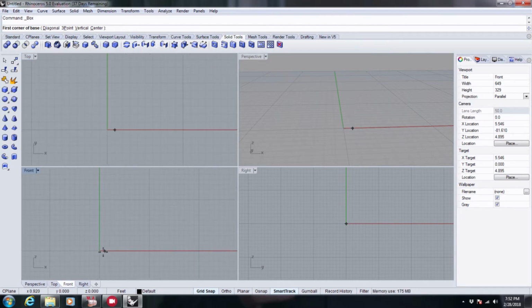Basically, you line all of your tiles up in a flat surface, then texture map them flat, and after they're texture mapped, you arrange all of your panels into their final position of the curve where they're going to go. So I'm going to do that right now.